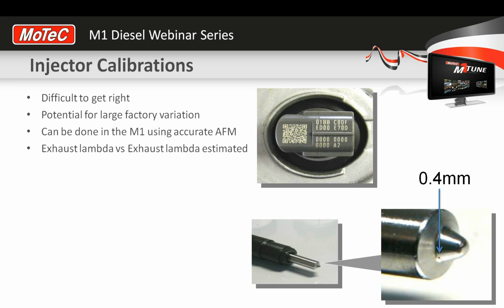And one of your other requirements of diesels is to run extremely high fuel pressures in order to have a very fine mist. That helps combustion start. So if we're going to run very high fuel pressure out multiple holes, yet deliver very small amounts of fuel, then we've got to have very, very small holes.